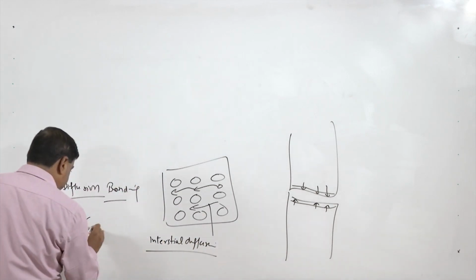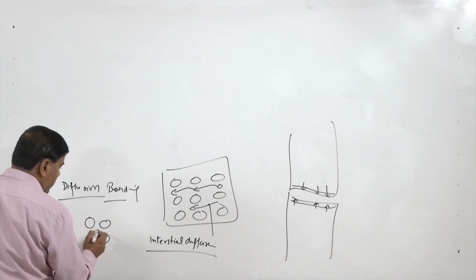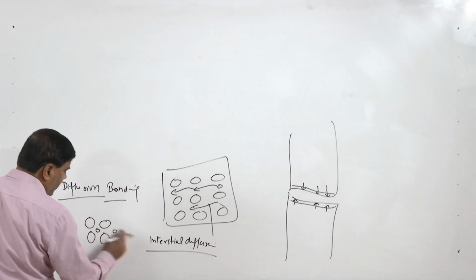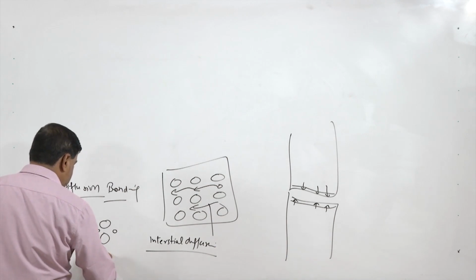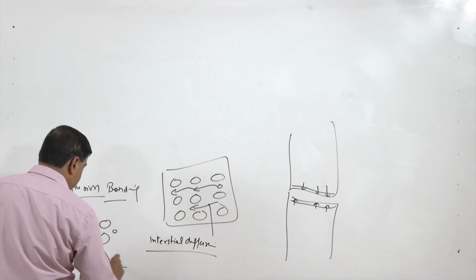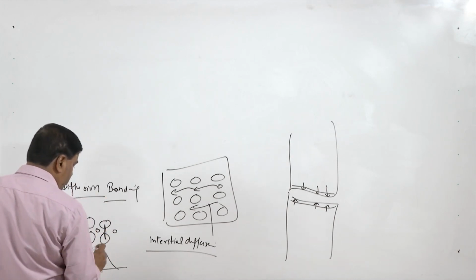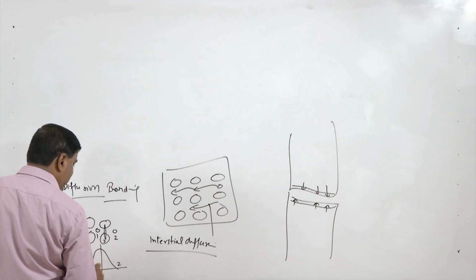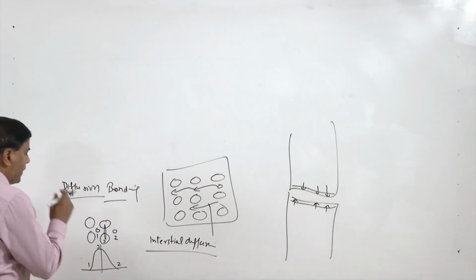we know that in a regular arrangement, say if this is the regular arrangement of the atoms, when one atom starts to move here, when it is in regular position, the strain energy associated with that is minimum, but when it reaches the center, the energy associated with this is maximum, say positions 1, 2 and 3. So, energy levels corresponding to 1 and 2 are less, and it is maximum when it reaches the center in the course of the diffusion.